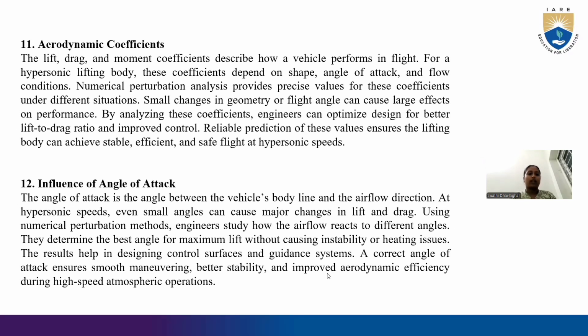Aerodynamic coefficients. The lift, drag, and moment coefficients describe how a vehicle performs in flight for a hypersonic lifting body. These coefficients depend on the shape, angle of attack, and flow conditions. Numerical analysis provides precise values of these coefficients under different situations. Small changes in geometry or flight angle can cause large changes in performance. By analyzing these coefficients, engineers can optimize design for better calibration and improved control. Reliable predictions of these values ensure the lifting body can achieve stable, efficient, and safe flight at hypersonic speed.